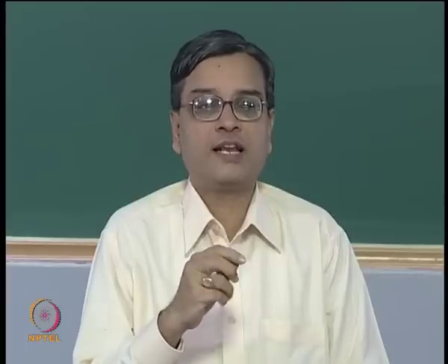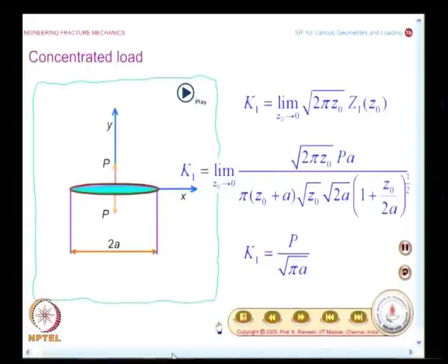And what we had seen in the last class, you had looked at the problem of a load at the crack surface. You have a concentrated load which is trying to open the crack faces, and for this case fortunately there was a stress function available. Once you have the stress function, it is possible to find the stress intensity factor by using this expression.